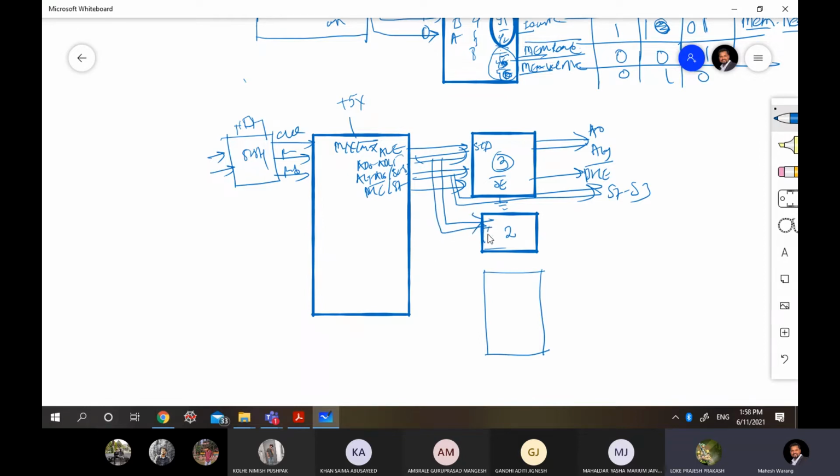Now the transceiver requires two signals, T and OE bar. To the T, we will connect DT/R bar. T means transmit. So the signal which will tell whether data is to be transmitted or received is DT/R bar. And OE bar we will connect to DEN bar. Understood? And at the output we'll simply get the data line. Since it is a data line, show it as bidirectional.